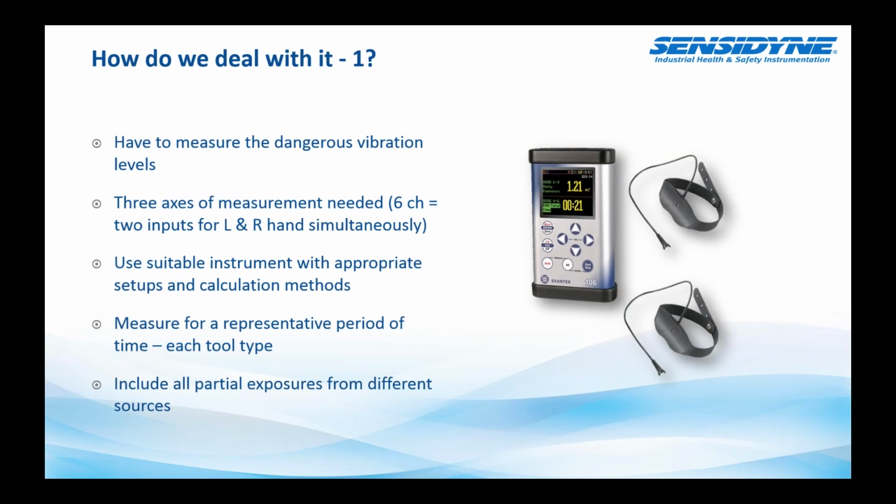We measure for a representative period of time. If a worker is going to use a number of different tools, then we really need to collect exposure information about each of the tools separately so that we can include all partial exposures from the different sources over the different durations. We can also deal with it with a smaller device,